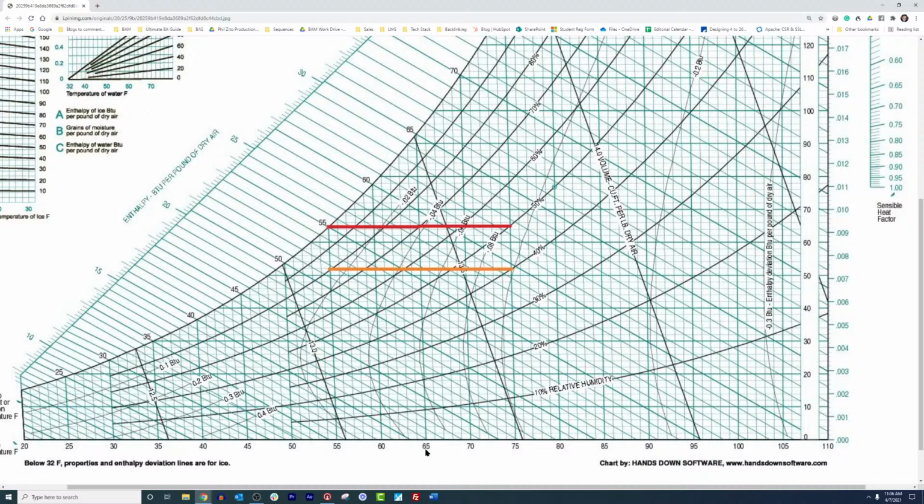So when you're comparing dry bulb, you're just looking and saying, hey, am I greater than 55 degrees, and am I less than 80 degrees? Okay, if so, enable my economizer. That can work in some regions of the United States and of the world, but when you get into very humid regions, you want to compare enthalpy. You want to look at what is your return enthalpy, what is the amount of BTUs in that air, and then what is your outside air enthalpy. And you want to decide which one is greater because that has a load effect on your system.